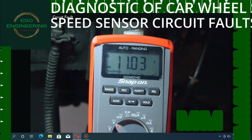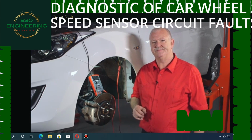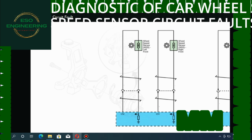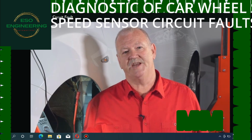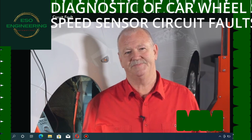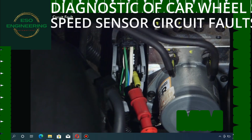If the voltage is low, then this will indicate that there is a resistance in the wiring, faulty connectors, or a possible module fault. If there's a harness connector in the circuit, you can test again at this point. If the voltage is now correct, then the resistance will be between the harness connector and the sensor connector. If the voltage is still low, proceed to the next connector in the circuit and retest. Back probing the module will be the last place to check the wiring. If the reading is still low, then the fault will be either the module connector or the module itself.